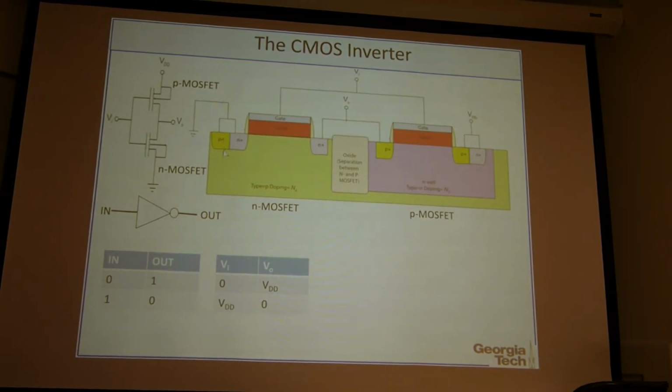So body contact is here. For the P-type substrate, you can have a P plus doping region as a body contact. So this is body contact. And then you ground the N plus source and the P plus body together. Or in the circuit symbol, you can ground this S and B together to the ground.